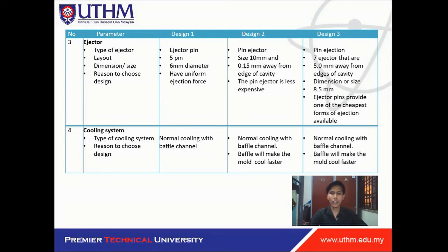And next is the cooling system. For design 1, we are using normal cooling with baffle channel. Design 2, normal cooling with baffle channel, because baffle will make the mold cool faster. And for design 3, we are using normal cooling with baffle channel, and because of the same reason, baffle will make the mold cool faster.